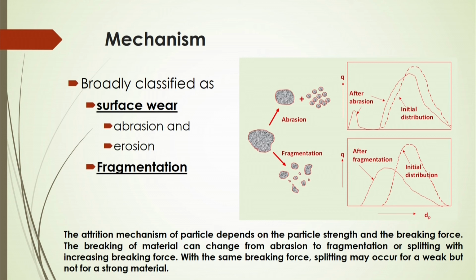The attrition mechanism of particles depends on the particle strength and the breaking force. The breaking of the material can change from abrasion to fragmentation, or you can say splitting, with increasing breaking force. With the same breaking force, splitting may occur for a weak, but not for a strong material.